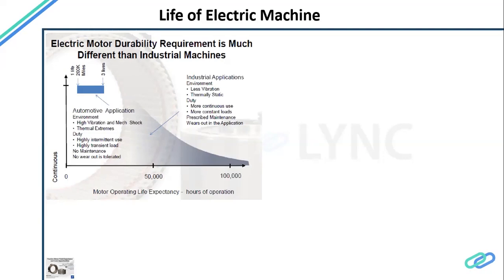Say different specifications for the material to be considered when we consider the electric steel, for example. At high speed, like 12,000 rpm, 15,000 rpm, 18,000 rpm, those rotor laminations have narrow bridges, and they all have to hold those windings or magnets.